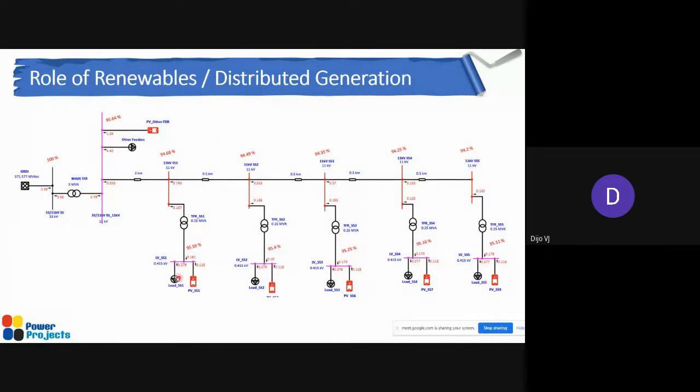Okay, you can see here. The loading we maintain the same 50%, maybe I think in this case 30%. The loading is more when you talk about only this, but here some generators are there. PV generation is added here, which gives almost 180 kilowatt. So the power required from the transformer or the grid is only 181, though the overall power requirement has increased to 279, more than this 250 kVA. The transformer is not getting overloaded, right? It is still taking only 187 because you have solar generation on the local bus itself, so it is reduced.